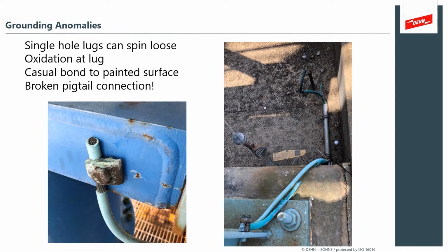And so you might be experiencing instrumentation problems and you're troubleshooting your instruments, and it's not the instrument, it's the earthing and bonding. That's why it's really important to pay attention to these maintenance issues that you can visually inspect. These are the things that you have control of.